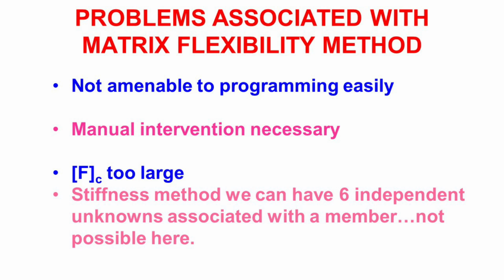But in the case of the flexibility approach, because forces are the main unknowns, we can at the most keep 3 unknowns because we have only 3 equilibrium equations. So this is another problem associated with the flexibility method.